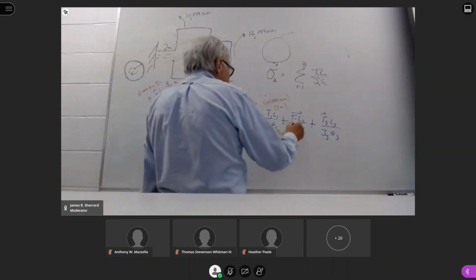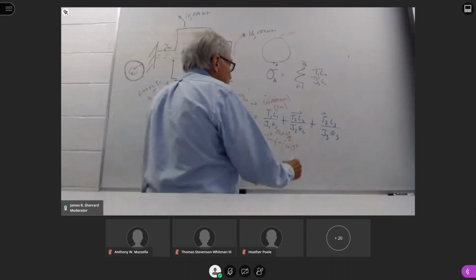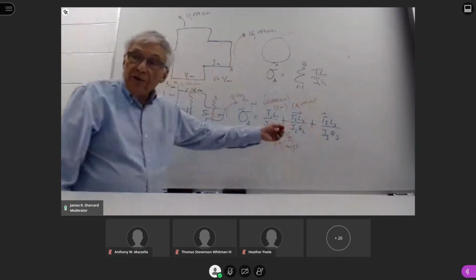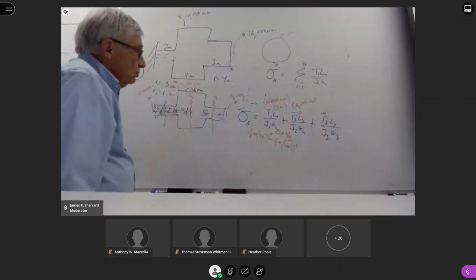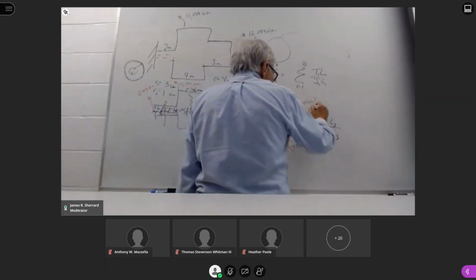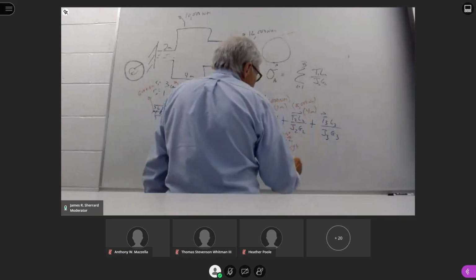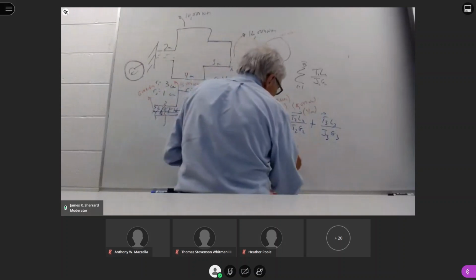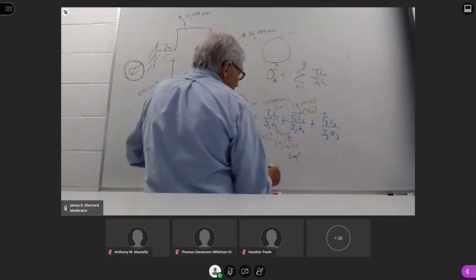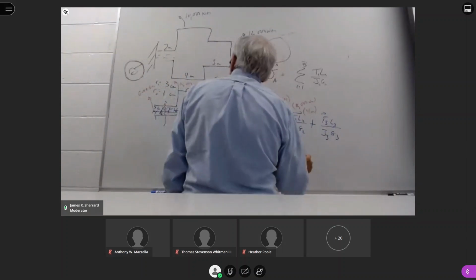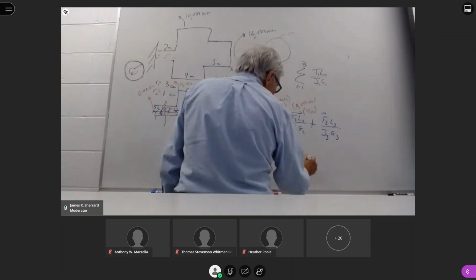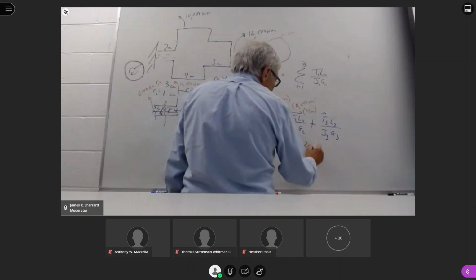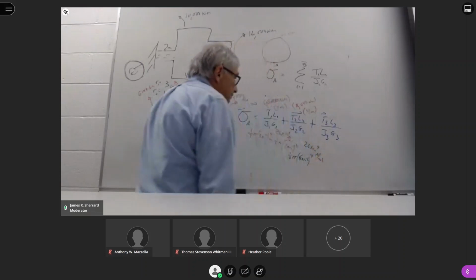I then look at the second section. The torque there was 16,000. And again, we got this number from the free body diagram. My length of this section was 4 meters. The J, since it's solid, was 1/2 pi times that R, which was 6 times 10 to the minus 2 raised to the 4th. G again, since it's the same material, is 26 times 10 to the 9th newtons per meter squared.